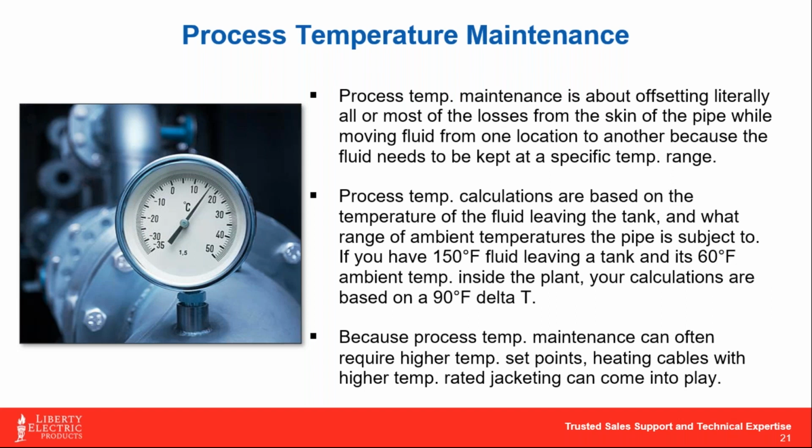Remember, I told you early on in this presentation that the intent of the cable is not to heat what is inside of the pipe. And the only time that can actually happen in most cases is if the heat trace system is still running and the fluid inside of your pipe stops. Okay, so as long as there's flow going through that pipe, typically you're not adding heat to anything that's inside of it.